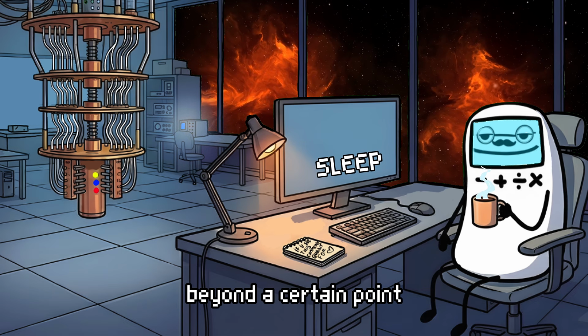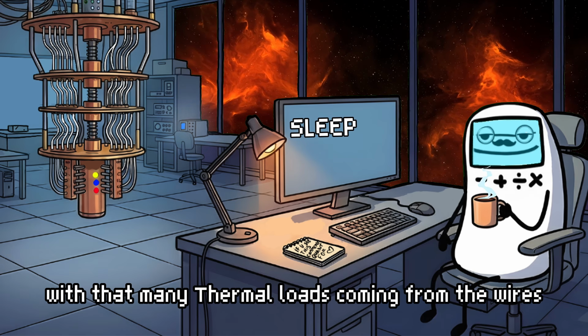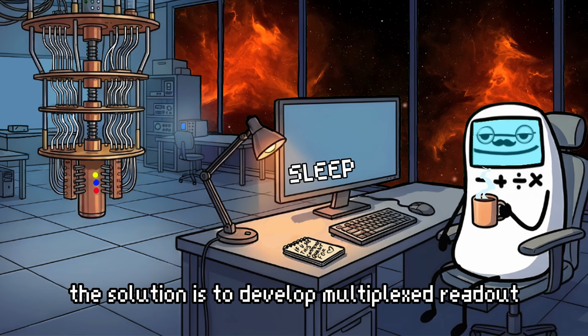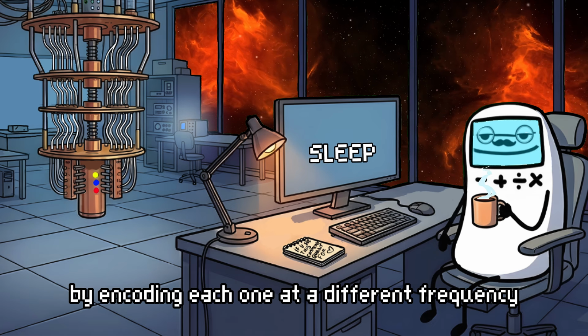Beyond a certain point, you just can't keep the thing cold enough with that many thermal loads coming from the wires. The solution is to develop multiplexed readout, where you can read many qubits through a single line by encoding each one at a different frequency.